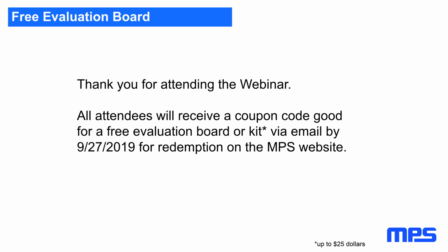Christian, how do you measure the input impedance of a DC-DC converter? The input impedance of a DC-DC converter is by definition negative, which means if I go higher with voltage, the current goes down, because the DC-DC converter makes constant power output. If efficiency is assumed constant, that means constant power input, and constant power input is actually a negative impedance.